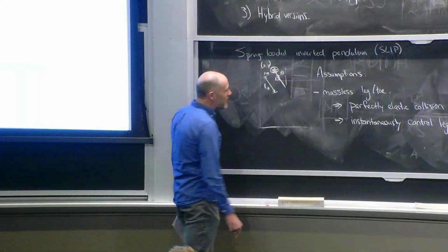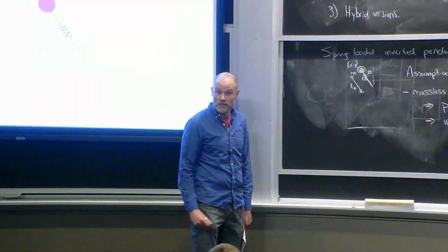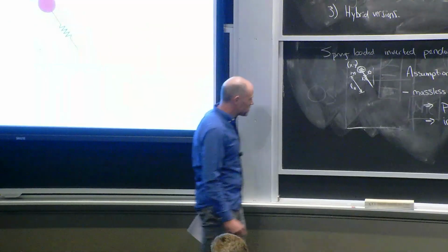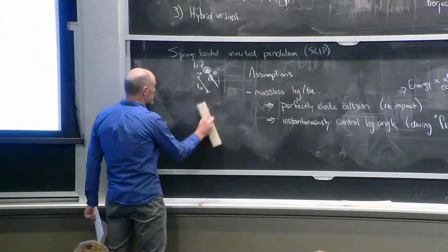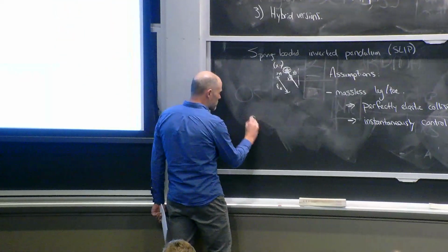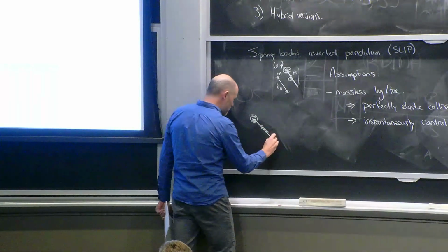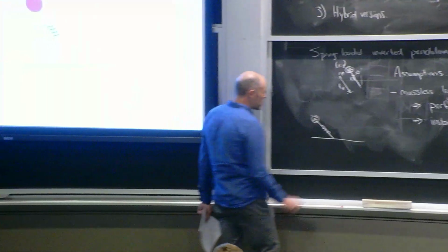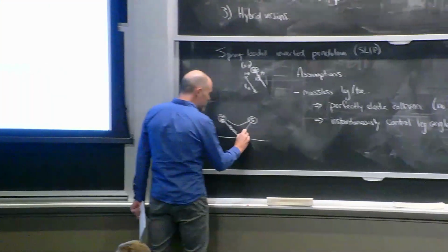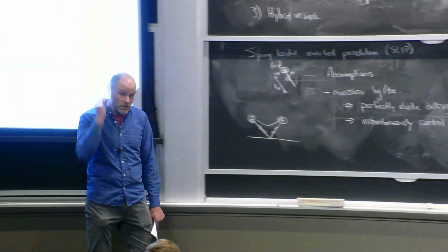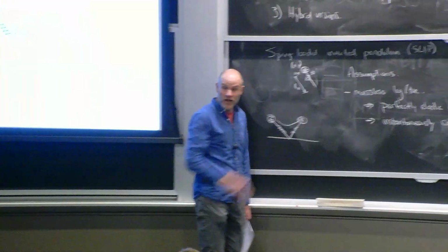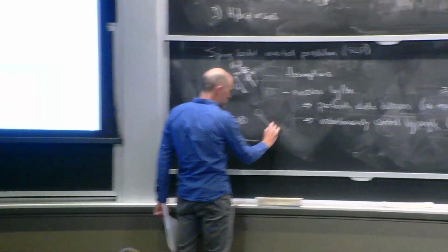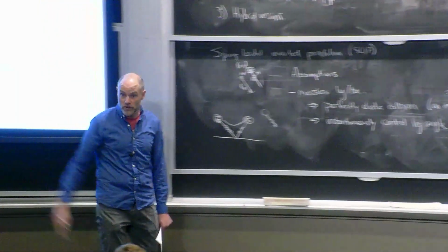Now the dynamics of this, which underlie the Raibert-style controllers, are a few things. There's a hopping height controller, which you'll study on your problem set. But the one I want to think about here is the foot placement controller. What Marc and his students observed in these SLIP models is that if you come down at a certain angle, there is an important touchdown angle where you have a perfect symmetry. As your spring compresses and then uncompresses, you'll leave at the opposite angle that you came in at. You'd expect at steady state that you're keeping a steady hop, and the angle you want to come down at gives you the symmetry and a periodic solution.